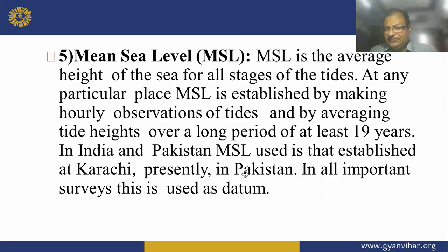So what is mean sea level, my dear boy? Mean sea level is the average height of the sea for all stages of the tides. For any particular place, MSL is established by making hourly observations of the tides over a long period of at least 19 years. In India and Pakistan, MSL is established at Karachi and Mumbai, the Gateway of India, and used in all important surveys.